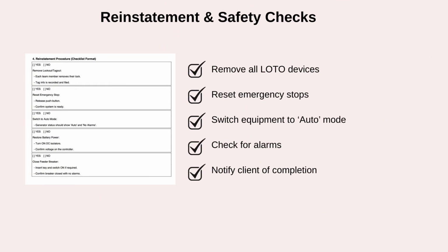Those LOTO devices can be removed, but only by the person who applied them. That's part of the safety protocol. Never skip this step or hand it off.